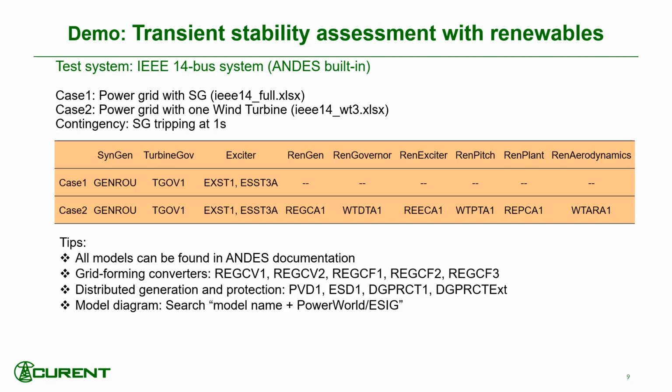We have the renewable generation model, REGCA1. We have the renewable governor model, WTDTA1. This is for a wind power model. And we have the renewable exciter model, REECA1. And then we have the renewable pitch model, renewable power plant model, and the renewable aerodynamic model.